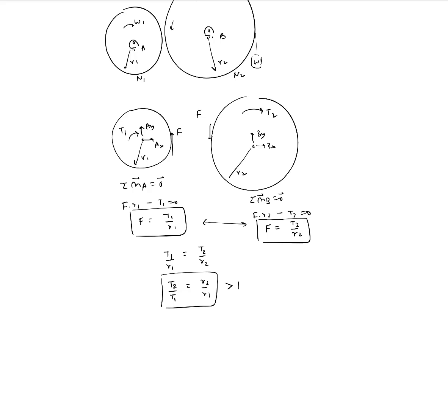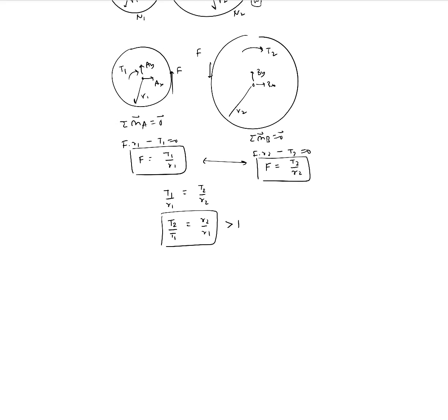Something like this would be useful if, let's say, your robot or machine had a larger torque requirement, and you were given a motor of a certain speed and a certain torque, but you needed more torque. In that case, you could use a gearing system going from a smaller gear to the larger gear, and then your output, which could be the wheels of your robot or something else connected to the load, could gain on the torque.